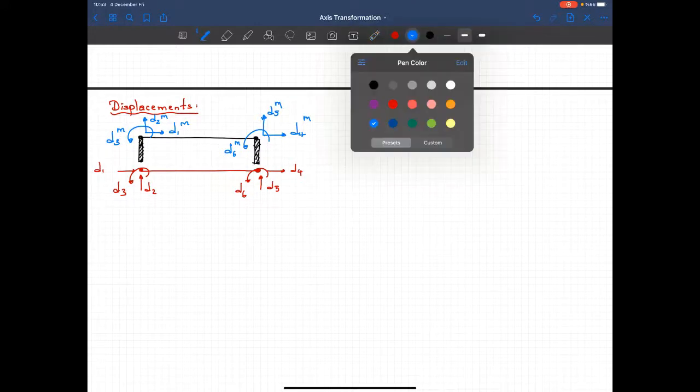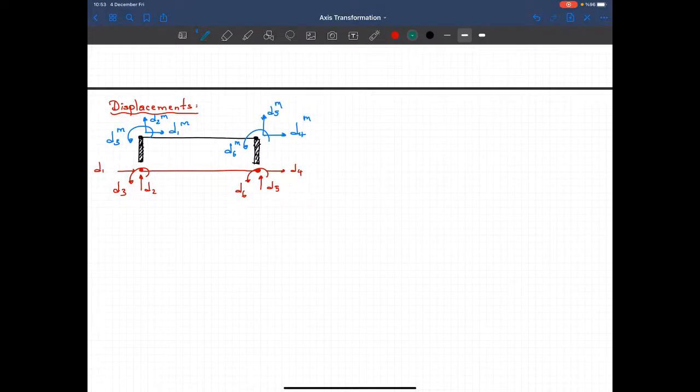So let's transfer these displacements to the end of that rigid member. So due to the compatibility I should have the same displacements here. This is D6, D1, D2, and D3. And then I will need to relate these displacements with the displacements of the members at the top.